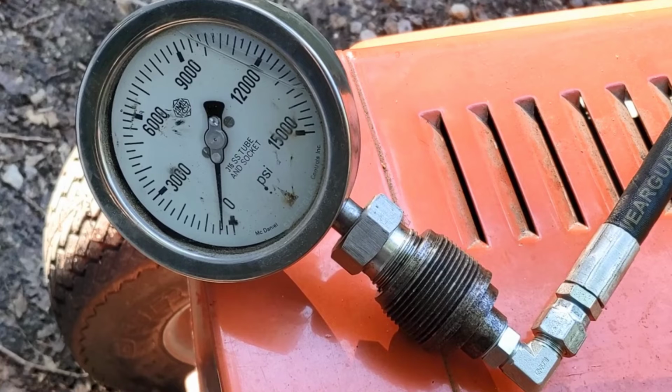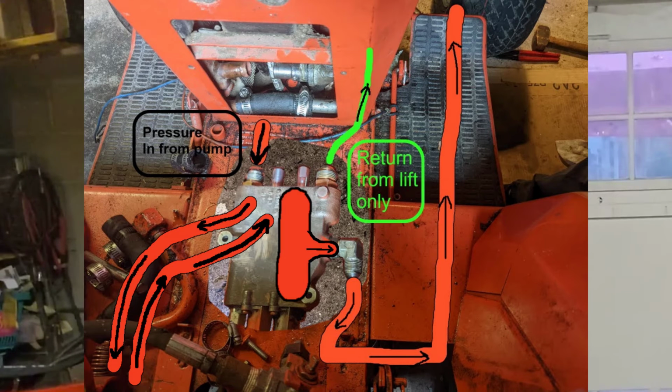And that was the ugly surprise, though if I were smart, I should have anticipated it. Remember how the flow works going through the travel control valve. Oil enters the travel motor galley, then dumps from that galley into the lift circuit galley, and then goes from that galley out the power beyond port.